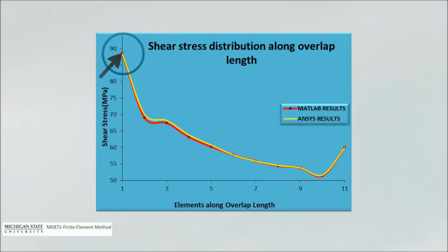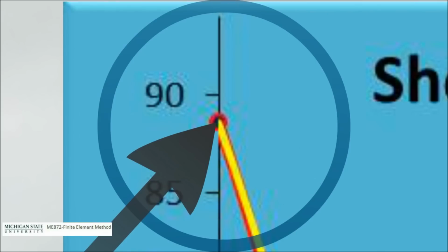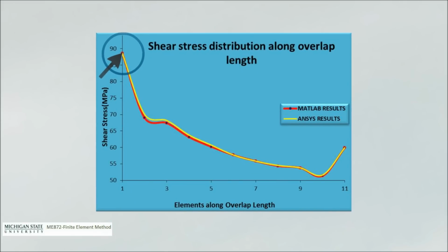Analysis shows that shear stress of adhesive at aluminum end is high, which is a less stiff material, and it progressively decreases to the other end. So if damage occurs, it will initiate at this point. Results are in compliance with ANSYS results with maximum error percentage of 1.47. Here, an uneven stress distribution is seen near the ends of the adhesive.